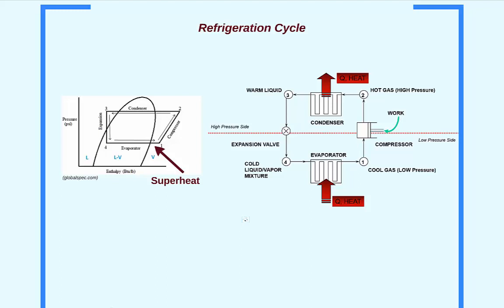At this point in the cycle, the refrigerant has all the energy that was absorbed in the form of heat from the evaporator, as well as the energy added in the form of work from the compressor. We need to release this energy before we can absorb more heat. As refrigerant moves through the condenser, heat is rejected to the outdoors.